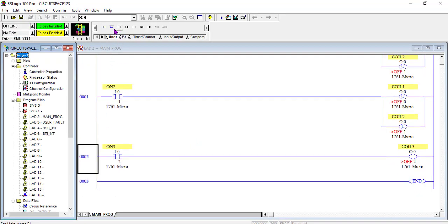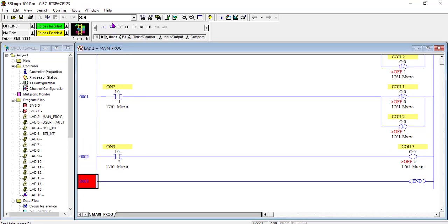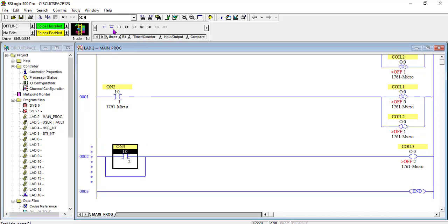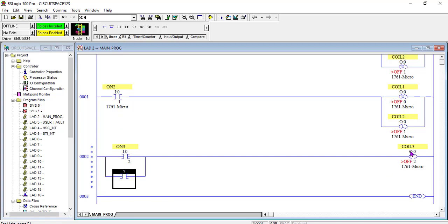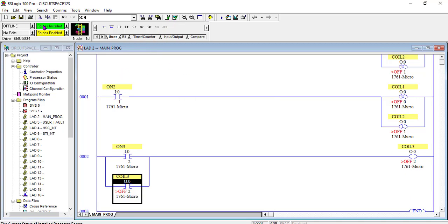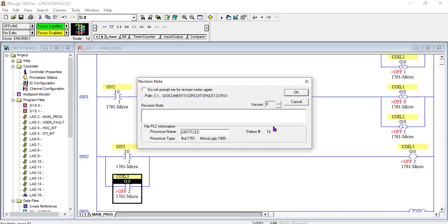So what we'll do is take a branch, and it has to go red. We put this inside. Then we take a contact in the branch and carry this address to here. That's all. Anytime this energizes, this closes, and if I remove my hand from this, it's already a parallel path to the output. So I verify the project, no error. Then I download it to the PLC.